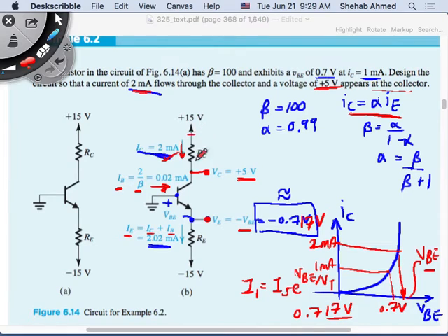So I have the voltages across the resistor here and the current through it, so I can find the resistor values in both cases. And now you need to confirm. So we confirm that this is now forward biased. Is this junction reverse biased? Remember, this is an NPN transistor. The base was 0.7 volts higher than the emitter, which means I have forward biased this, which is fine.